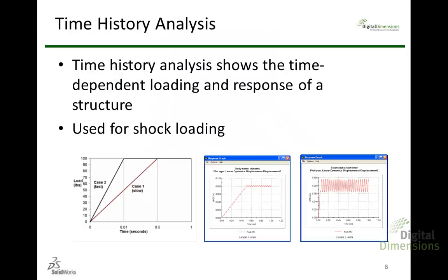So the first forced vibration simulation we're going to do is going to be a time history analysis. Time history analysis shows the time-dependent loading and the time-dependent response of a structure. It's typically used for shock loading. So notice the two time curves, or load curves, that you see on the left-hand side of this slide. I've got a fast loading case and a slow loading case. We can basically add any type of time curve into your load definition and find out how your structure is going to respond. So let me show you how to do that.